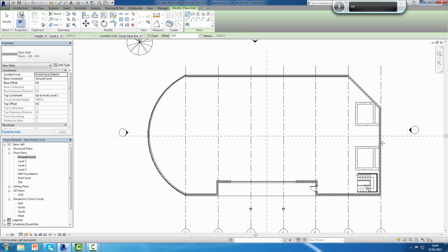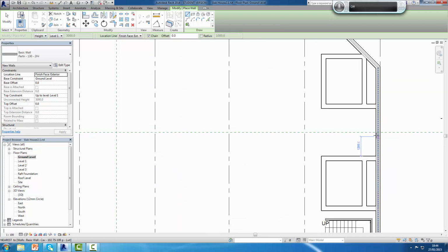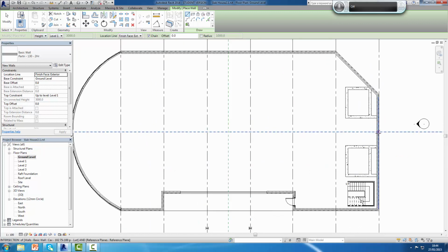The first thing I want to do is pick in this area here. I want to pick at that point there because that is going to make sure that wall is in the center. But if you'll notice what it'll do, I want not that particular term because I didn't put it in. So I've got to concentrate. I do apologise. So what I want to do is pick the wall, but in here I want to put a 4-foot offset in. I want to put 1200 millimeters in there, and again make sure that I press enter just to make sure that it's got it in.